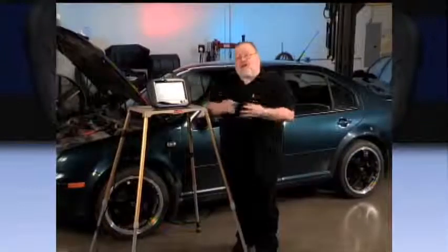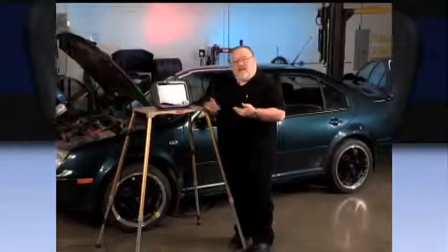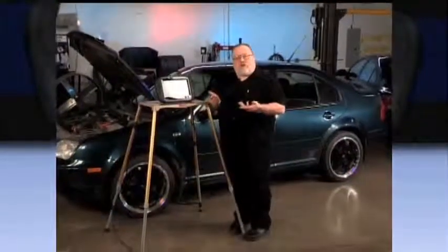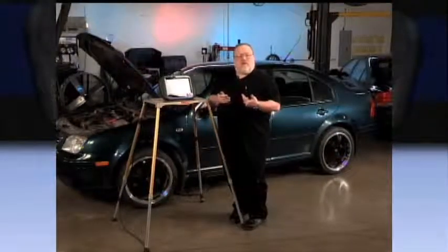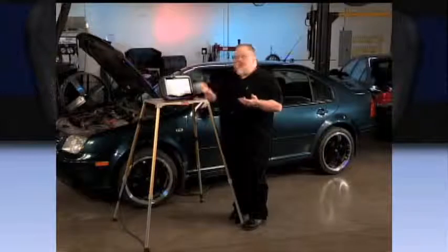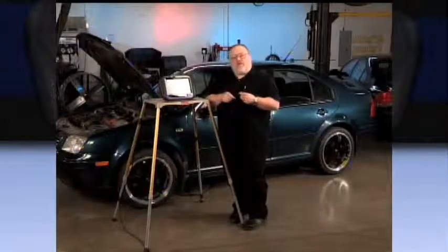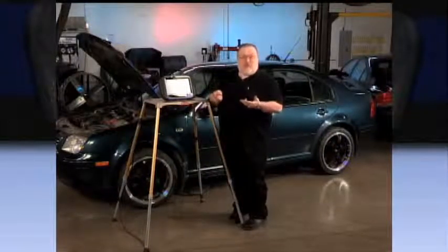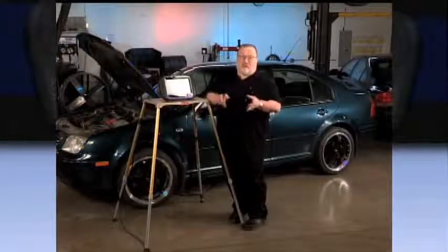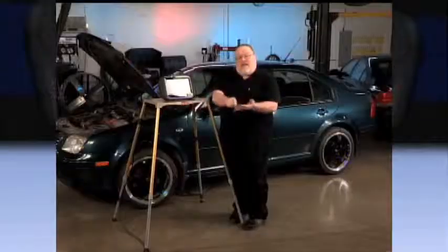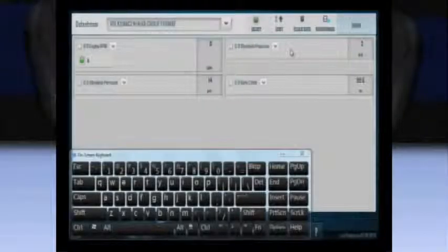So in this case, what I'd be looking for at wide open throttle, somewhere in the neighborhood of about 4,000 RPM under full load, about 2,100 millibars of boost. And as you can see, if the computer is asking for 2,100 millibars of boost and I only have 1,200 millibars of boost, I've basically got no boost on this vehicle at all, meaning that I've got a problem either, once again, with the engine not being able to breathe properly or with turbo function.